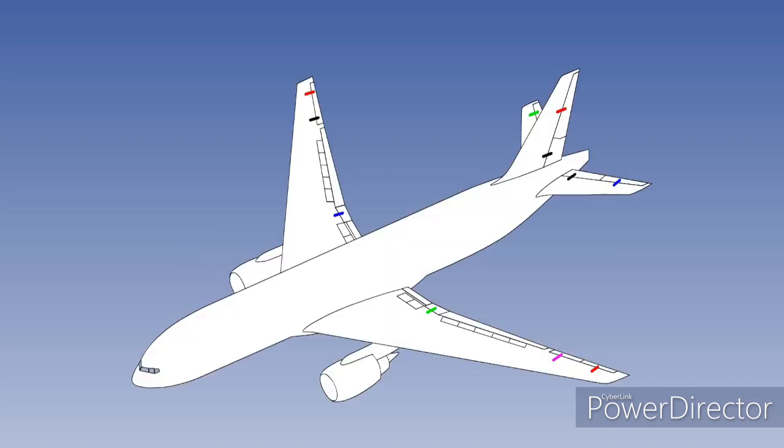Redundancy involves the use of multiple, completely independent hydraulic systems to power the flight controls. Each control surface can also be split with each segment powered by a separate hydraulic system. For modern jet transport with only 3, and more commonly 2, gas turbine engines, a ram air turbine, or RAT, is fitted to maintain adequate redundancy. In the event of an engine and/or a pump failure, the RAT can be deployed to provide a hydraulic flow to the primary flying controls only.